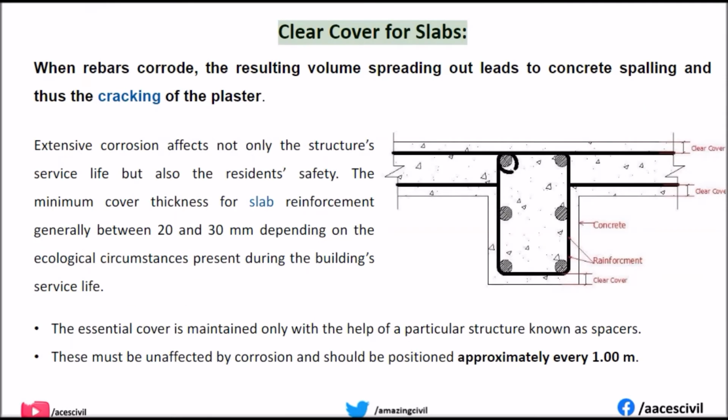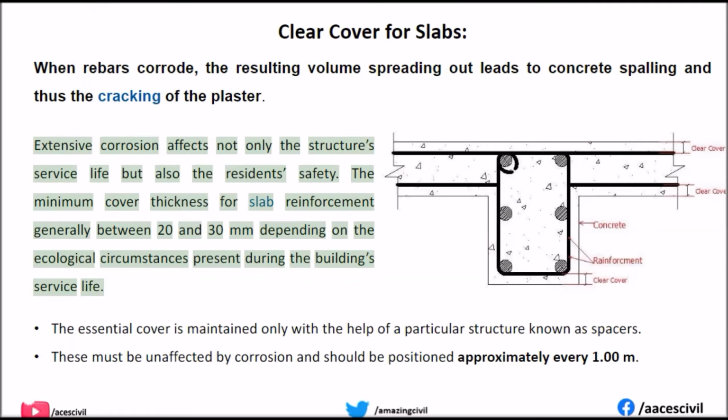Clear cover for slabs. When rebars corrode, the resulting volume expansion leads to concrete spalling and thus the cracking of the plaster. Extensive corrosion affects not only the structure's service life but also the residents' safety.